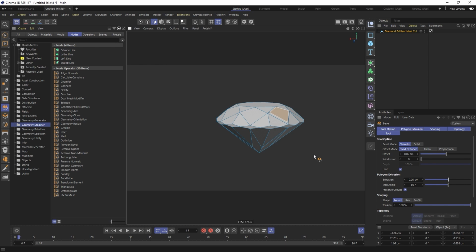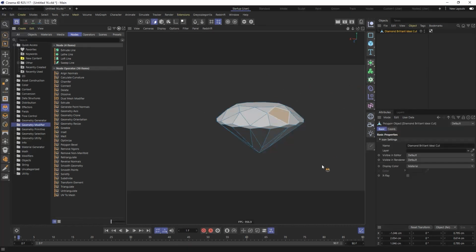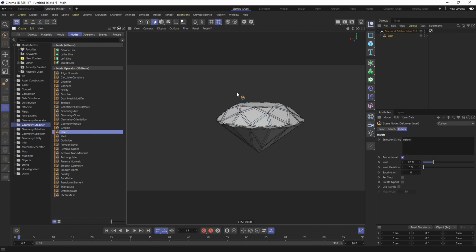You have to keep that in mind when you're working with some of these procedural modeling techniques that are unlocked with capsules. So hitting undo, let's say we just want to do something real simple. Let's say I want to do an overall inner extrude on everything. Let's deselect all the polygons and then select an inset. So with the inset, you see every single one, even though nothing was selected, it's like everything was.